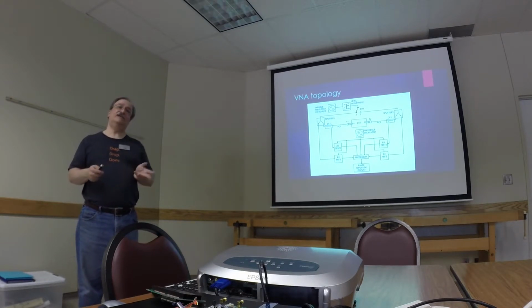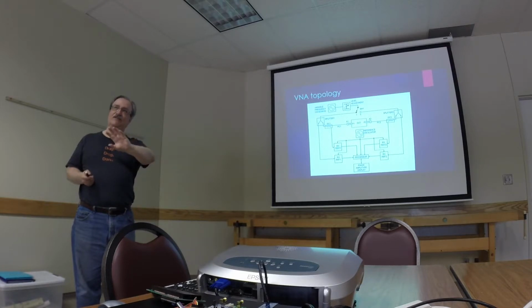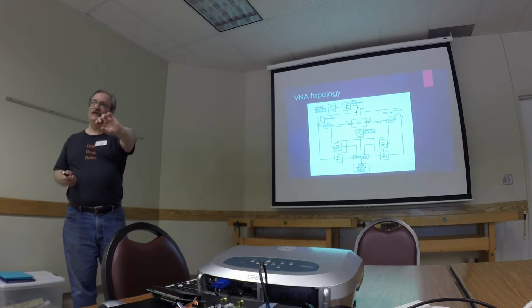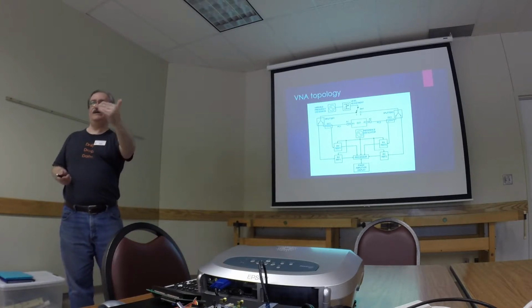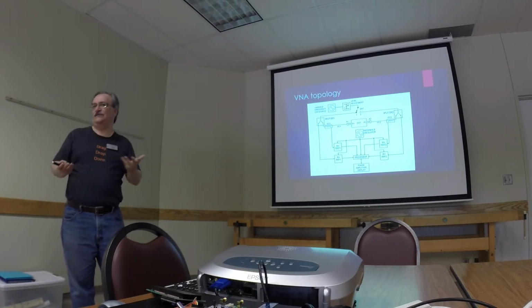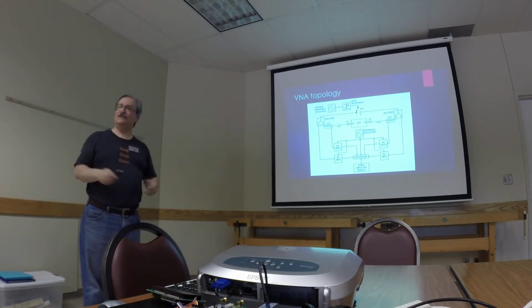The reason for that is when you get up into the gigahertz range, you can't assume what's going on with phase in that cable. So as you send the source signal, things could be happening to it at multiple gigahertz, let's say 18 gigahertz, that you might assume wouldn't happen, but in fact are. And so when you go to make a measurement coming back around on the loop, your point of reference could have shifted. So in HF frequencies, you don't have to worry about any of that, which is nice.